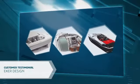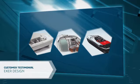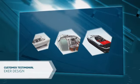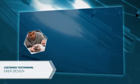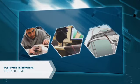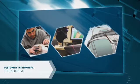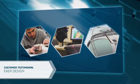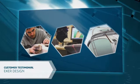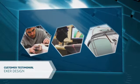Ecker Design is Scandinavia's leading provider of turnkey mechanical and industrial design services. The new Hydrolift C27 was designed and constructed in CATIA. The development process begins by building a scale model by hand and then scanning the surfaces. Engineers then start to transform the scan into a ready-to-be-manufactured part with Class A surfaces. CATIA is then used to model all the standard parts and to design the custom parts in fiberglass and stainless steel. By modeling the entire product in CATIA, the design team had full control as they sought to obtain a design that would yield the best performance.